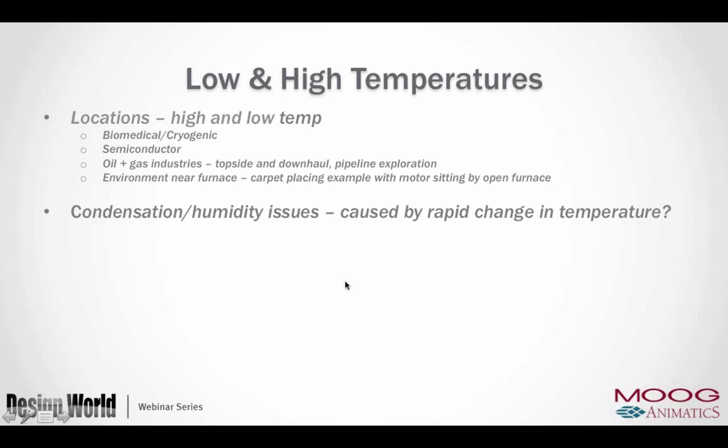Okay, condensation and humidity issues. This is caused by rapid change in temperatures. If you've got something that's very hot, goes to cold at night and back to hot during the day, moisture will condense on the surface of those products. It may get inside of the products, in which case your means of feedback, such as an optical encoder, you wouldn't want to use a standard optical encoder where that could happen. You may have steam from hot washdown to kill bacteria, but that's not sustained typically. So that's a case where somebody will say, can you handle boiling water?